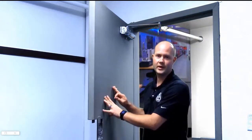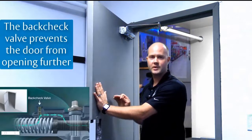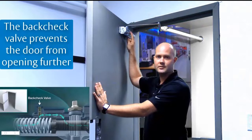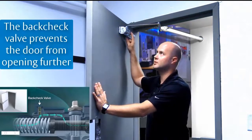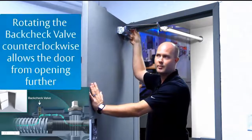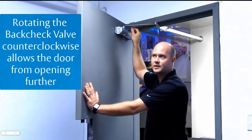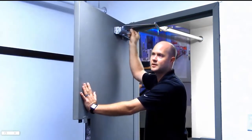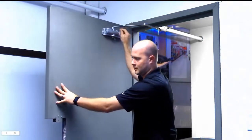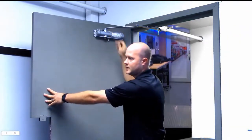So with the door open now, you notice that I'm putting pressure on the door, but the door's not opening. That's because I'm restricting oil from passing through the back check valve. When oil is restricted, the door doesn't open. I need to take my 1/8" Allen wrench and actually back that valve out. So a minute ago, we turned it clockwise. Now we're going to turn it counterclockwise, and all of a sudden, the door will start to open further. Okay, you can feel that cushion that we need.